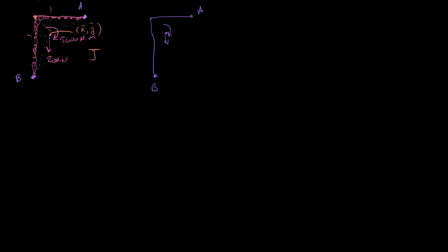So the loads here are going to be the constant shear for both A and B. That's our shear due to V over A, which is 80 over T, which we just calculated. So that's the yellow portion. And then we're going to have another portion that's due to that applied torque or torsional load on that joint. So this distance here is 45. This distance here is 20 from our calculations.